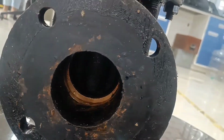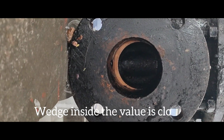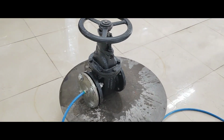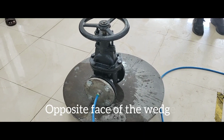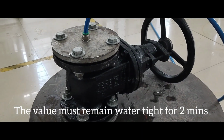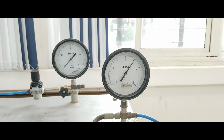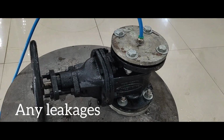In the second and third test, the wedge inside the valve is closed. Pressure is applied on one face of the wedge in the second test. Then in the third test, pressure is applied on the opposite face of the wedge. The valve must remain watertight for 2 minutes. During testing, the pressure gauge must not drop below the test pressure and it should not have any leakages and detachments.